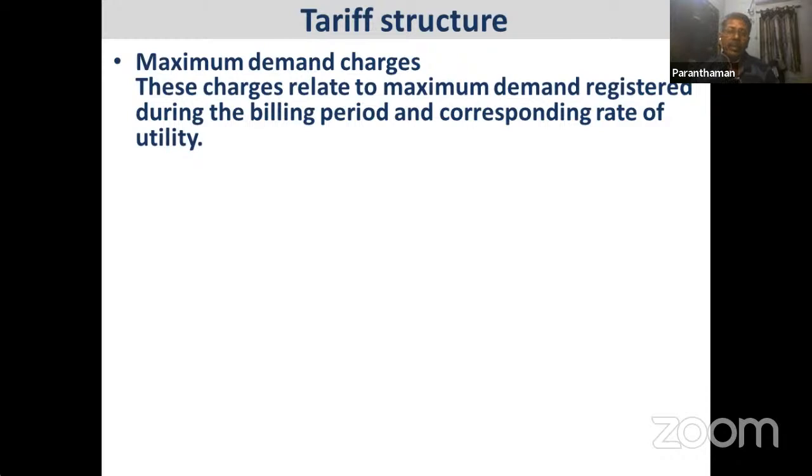If we diversify our loads or equally distribute our loads, the maximum demand will naturally come down. Suppose we can reduce from 17,000 megawatt demand to 16,000, already I told you, nearly 8,000 crores of rupees. So it is a direct impact, not only on the generation, it is also required for the entire network, LT, HT network and transformers.